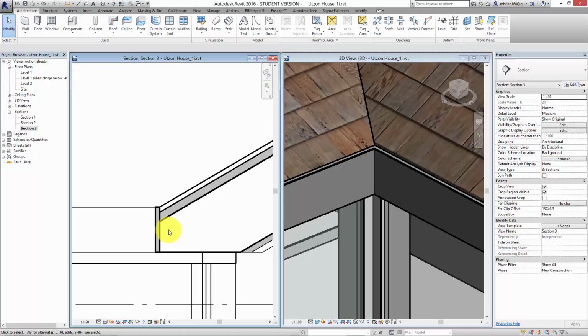We can add a profile to that. We could make it any shape we potentially want it to be. So at the moment they give you two options, 19 millimeters by 200 and 25 by 250. But it's just a rectangle profile added to a sweep. So you can change the profile if you want.